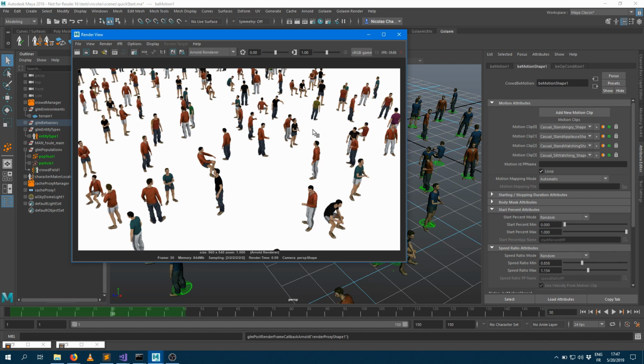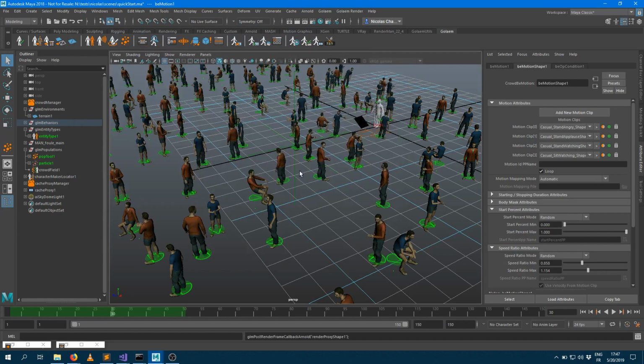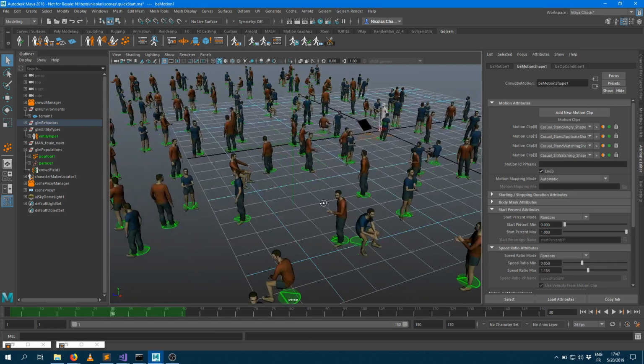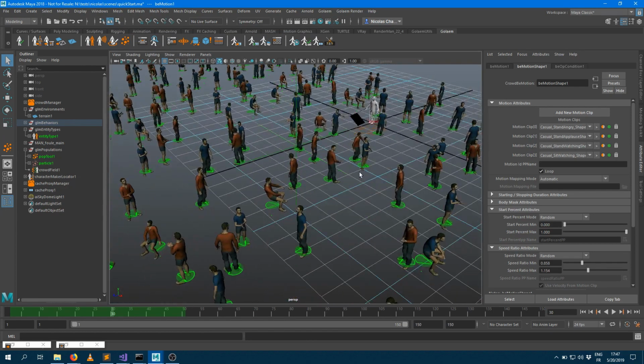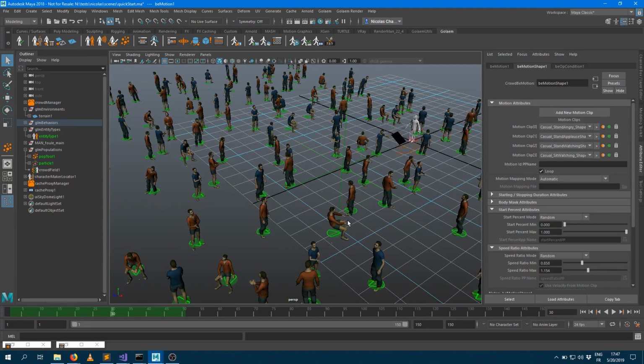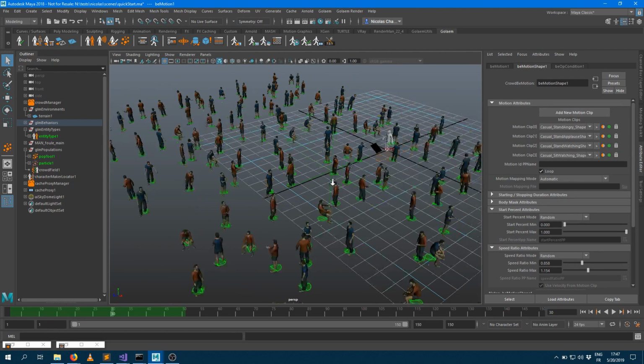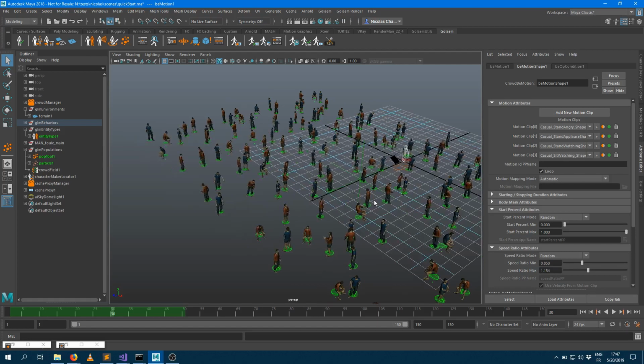And here we go. As you can see now, your characters are being rendered with the right posture, which corresponds to the animation they are playing. So the last step here is to apply some layout modification to the characters. Golem comes with a really powerful layout tool, which allows you, once your simulation has been exported, to edit what's going on. It allows you to change the character position, rotation, and scale, but also to duplicate a couple of characters or even change their postures or their mesh assignment.